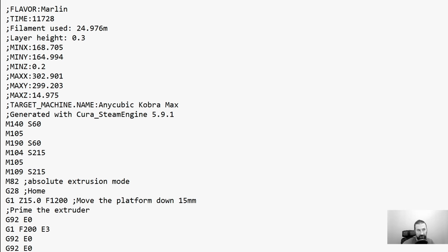But it is important to understand that these flavors are actually not important at all. Most G-code is exactly the same most of the time. And if you have some differences, you will notice that it's not that dangerous. You can break some things if you do very strange things, like driving your nozzle into negative values and hitting your print bed. You need to understand a little bit of the coordinate system which goes on here.